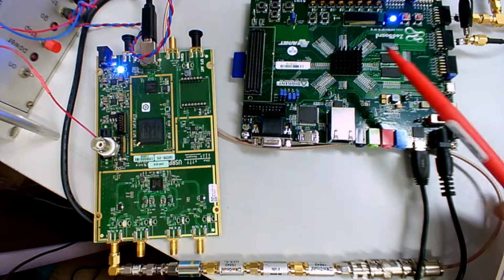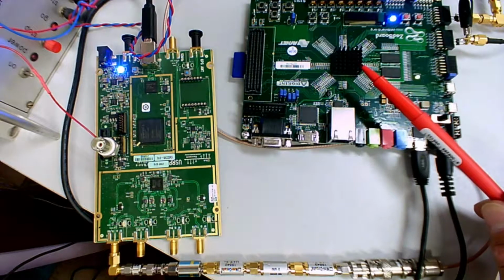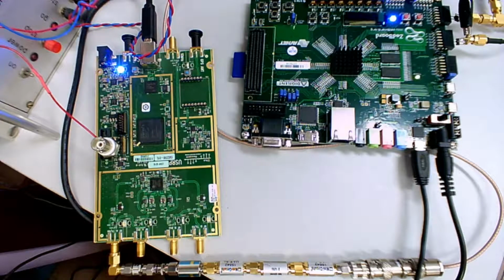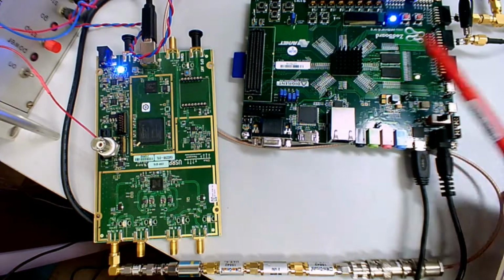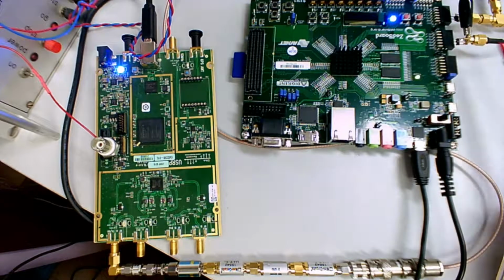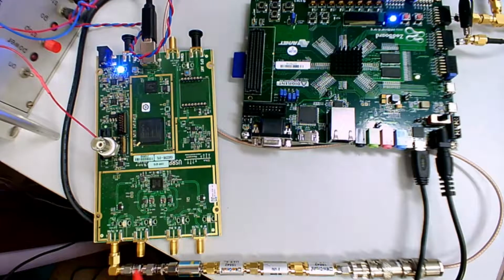And the clock of this FPGA is not the same one as the one clocking the B210 software-defined radio receiver. So this frequency offset means that despite a 70 MHz nominal frequency, transmission occurs over here and is fed through this hefty set of attenuators to make sure we don't damage the input of B210. The 70 MHz nominal input is not exactly at 70 MHz on the input of this radio frequency front end over here.